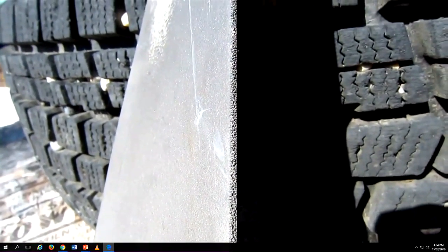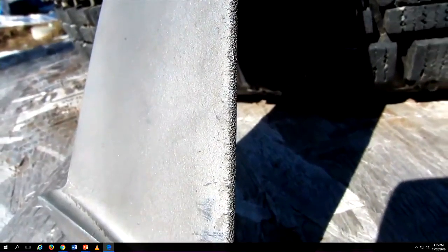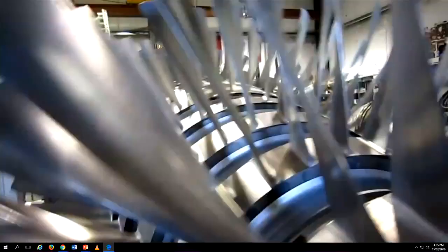7,200, 7,400 RPM. To repair this, all this would have to be filed away and then repolished to a nice smooth leading edge for the airflow. This one could be fixed, but because of the root wear, we junked it. This is why intake air filtration is so important for an industrial turbine engine. They run for much longer periods of time between maintenance than an aircraft engine.